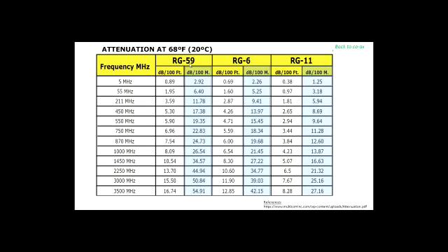See here? So let's see, our RG59, here's one per 100 feet, or the other one's per 100 meters, whichever you choose. So let's look at the feet here. So 5 megahertz is going to attenuate 0.89 dB per 100 feet. Okay. Every 100 feet, you're going to get, well, basically almost 1 dB, so 0.9 dB loss. Now, when you have the high frequencies here, per 100 feet, you're going to lose 16 dB. Remember, 3 dB is half of the signal. So 16 dB is, well, you just do the calculation here, right? Now, so here is RG59.